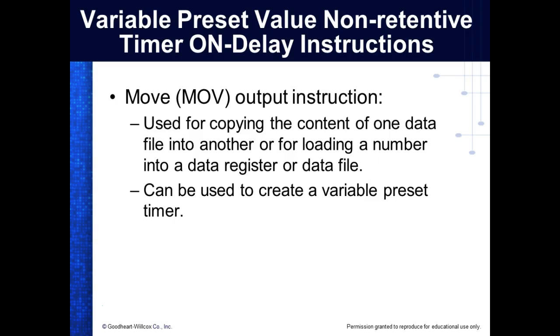The move instruction, this is an extremely powerful instruction. The move instruction is an output instruction. It's used for copying the contents of one data file into another data file, or for loading numbers into data files. So we can load the preset with this instruction right here. We can preload the accumulator with this instruction right here.